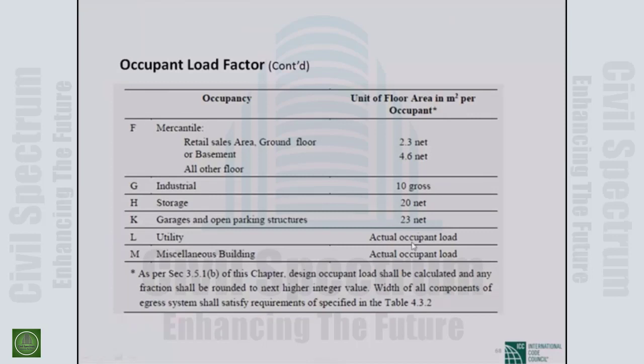But in the labor law, they say 10 meter cube. That is due to human comfort. You need air per person of 10 meter cube. If I divide by the height of the building, it is 3.6 for industry, it becomes about 2.6, 2.8. As per labor law, it is 2.8, and that is followed by garments factories at this moment.